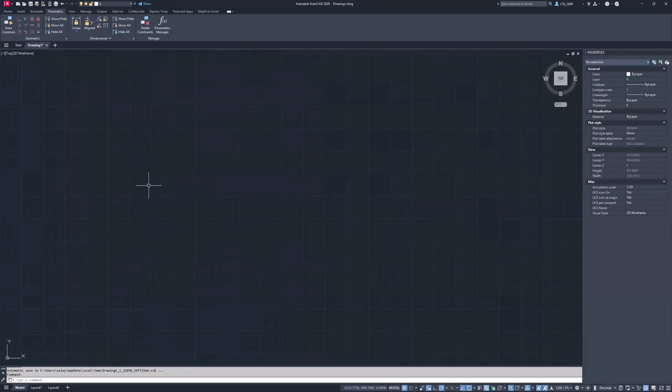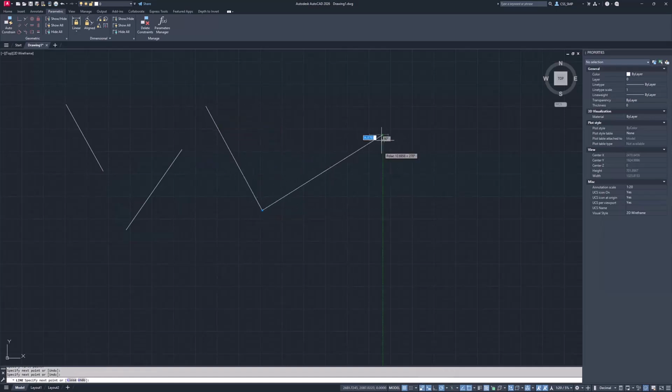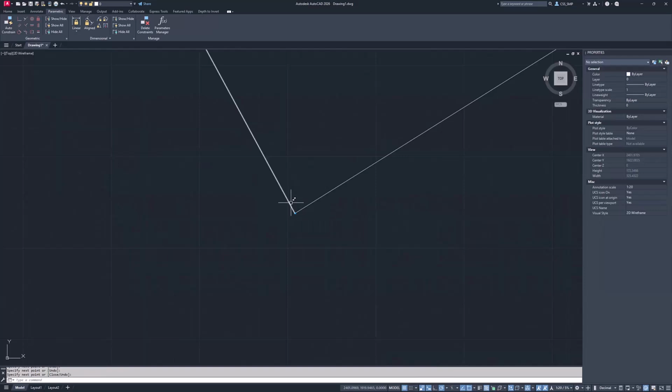So with AutoCAD, when we draw lines, you'll see that when we grab this line here, we're able to move this away. When we're working with AutoCAD, we can also turn on the infer constraints down here. And if I do that same thing again, line, click and click, you'll see that there's been a little grip that's been placed on the end here. And if I hover over here, we can see the infer constraints button.